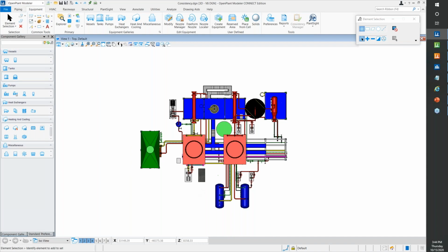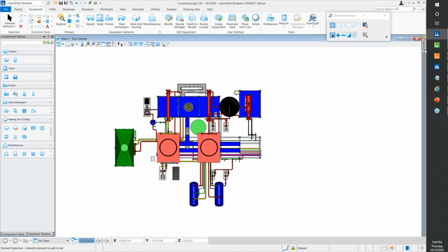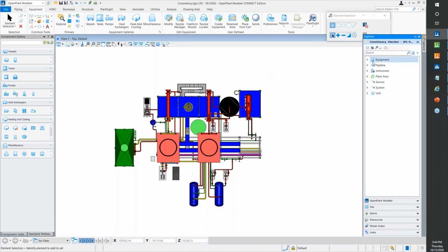And coming to the reuse of data, here we go. Whatever data I have created in the P&ID can be seen over here, listed with a color code. Here you can see that pump PMP3102, which we created in the P&ID, is presented in red color, which confirms that it is present in the P&ID but not in the 3D environment.